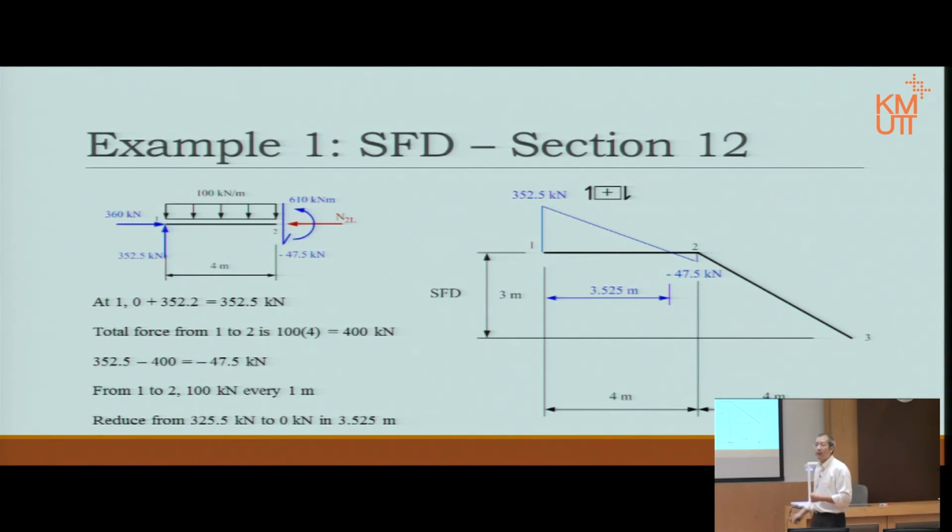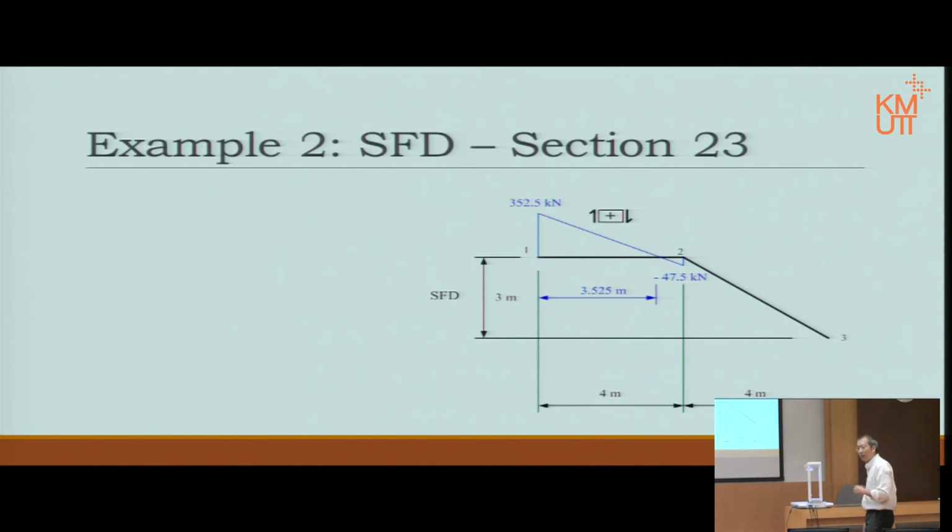Basically, that number divided by 100. Normal ratio taking. Okay. Now, again, we have already proved the shear force. We can use that to actually draw the bending moment diagram. Notice on the left-hand side of the picture, the free body diagram, there is no moment applied at point 1. So moment at point 1 will remain 0, and it changes with the shear force diagram only.